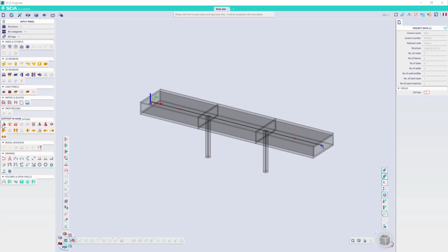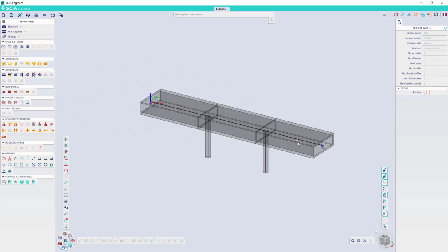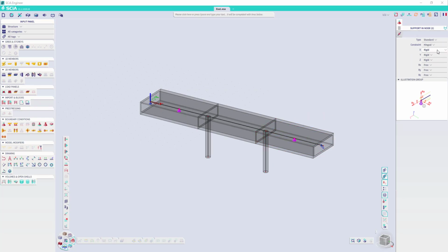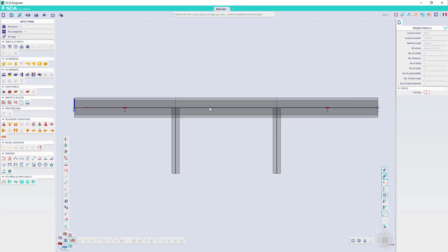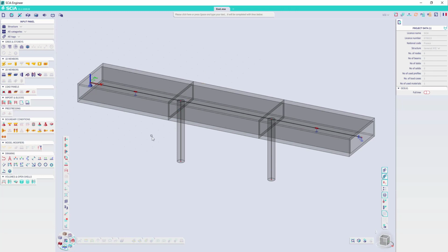And again, I can input a hinged support also here. For this support, I can also remove the hinged and lock only the vertical reaction. It's for this that we put it, just to sustain the structure vertically and temporarily. Okay, the structure is complete with all the elements that we want to input.